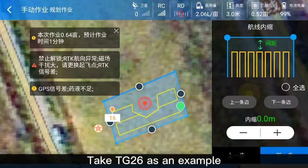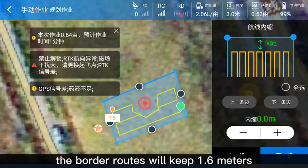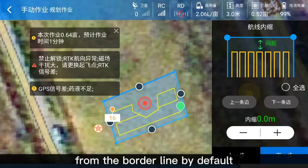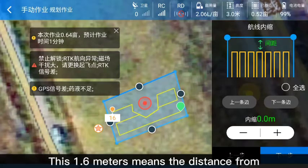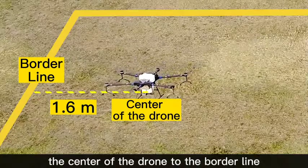Take TG26 as an example. In the autonomous mode, if we set the route retraction distance to 0 meter, the border routes will keep 1.6 meters from the borderline by default, except the first route. This 1.6 meters means the distance from the center of the drone to the borderline.